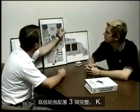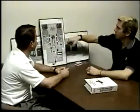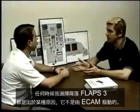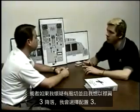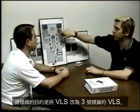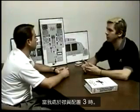Explain to me config 3 versus full. Okay? We select config full for just about every approach that we do at United Airlines. First of all, most of the landings we do are full, so we want to select full. Anytime I elect to land flaps 3 for just a reason, it's not ECAM driven. For instance, I want to do flaps 3 for proficiency, or if I suspect wind shear and I want to land in flaps 3, I'll select config 3. What this will do is change VLS to a VLS for flaps 3, and then it'll allow me to slow to my managed approach speed when I'm in flaps configuration 3.